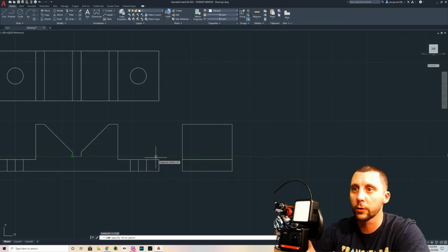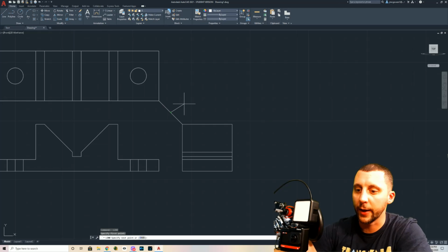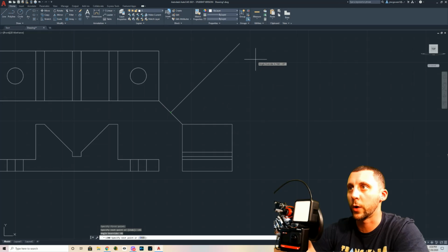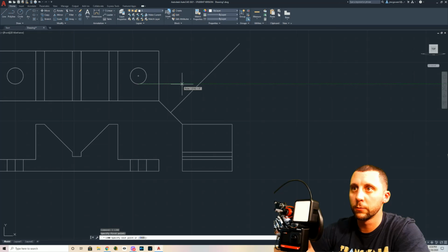So if I bring that all the way across, that's going to give me one hidden line. And then if I bring this one across, that's going to give me another hidden line. And then we should also have some hidden lines for, let's see, if you go like this, okay, and then you go like this at angle 45, I just want to explain why this happens, why this is the way that it is. So this one and this one, they actually flip over this 45, and that tells you where the position of them are in the next view.